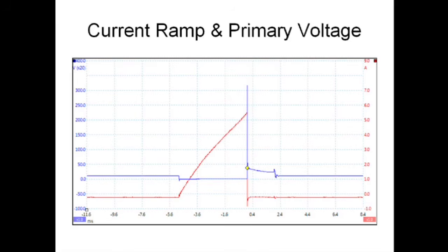Now we follow the red line coming up at about a 45-degree angle, and then all of a sudden it makes an abrupt downward turn. And if we look at the blue pattern, this is where the spark plug is fired, because the switching transistor was turned on, then turned off at the point of firing. So from the slight downward turn in the blue line, where we start our ramp up on the coil, to where we fire, would be known as the coil saturation or the coil dwell time.